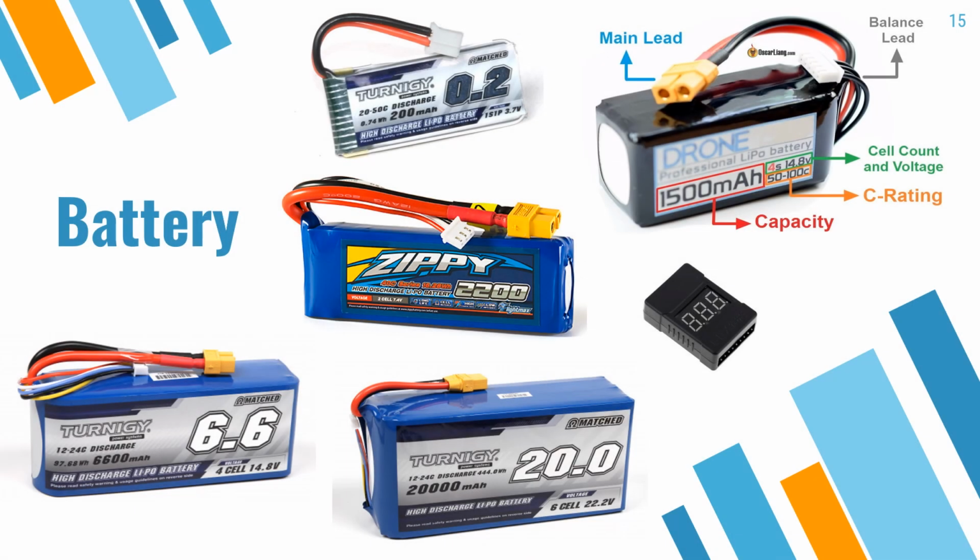Alright, last but not least, the battery. I've mentioned the battery multiple times before, and I think you guys all know what it does. It supplies power to all the electronics. Let's have a look at the picture above in the right corner. The first thing to consider is the voltage of the battery. Each battery has a number of cells, and this number of cells is represented by the so-called S number. In this case, it's a 4S battery, so that means that the battery has 4 cells.